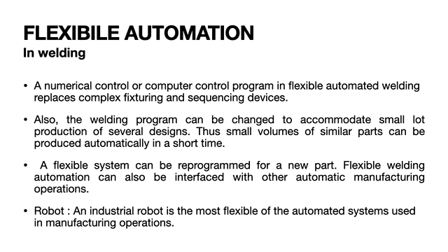Also, the welding program can be changed to accommodate even small load production of several designs. Whereas when we were discussing before, the flexibility for designing a new product was restricted due to the requirement of very costly jigs and fixtures. The small volumes of similar parts can be produced automatically in a very short time. A flexible system can also be reprogrammed very easily for designing or fabrication of a new product.